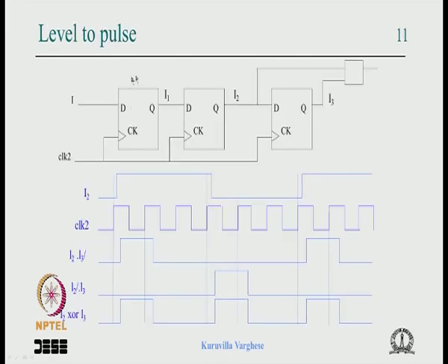So we do a synchronization for timing reasons, to avoid metastability in the flip flop. We have not discussed that, but for the time being just put a double stage synchronizer, which is nothing but the same clock and two flip flops in series. And here is what we do: you take I2, the input of the flip flop, and the output of the flip flop, and combine them.